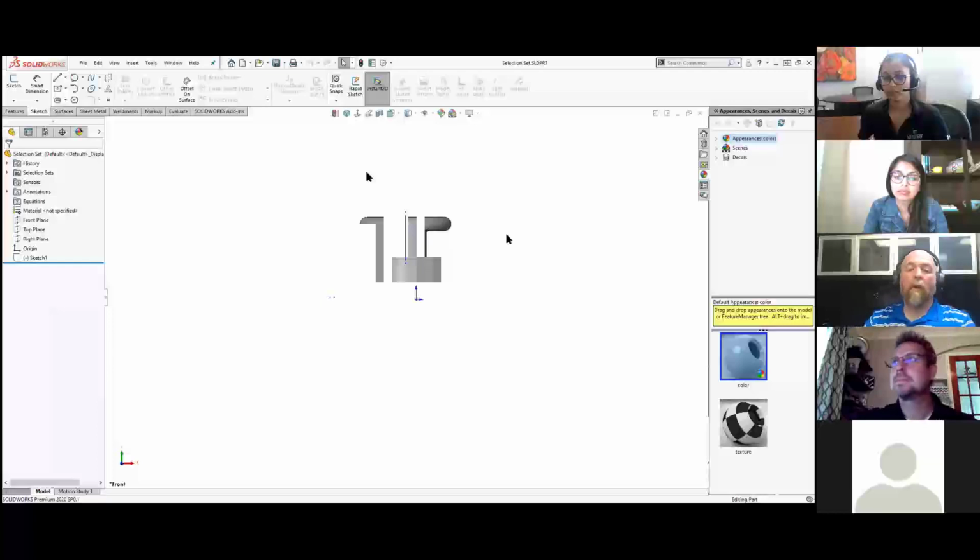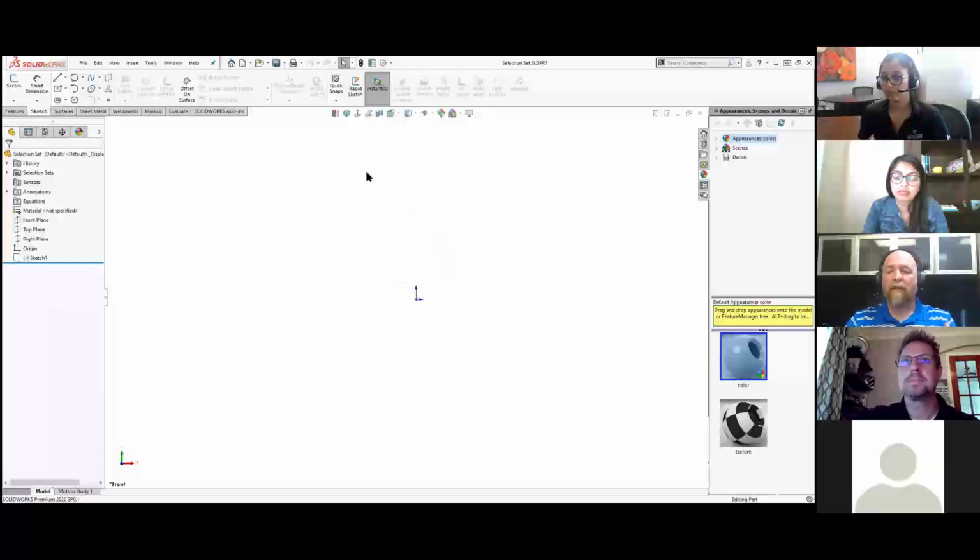I love these when I'm using one face in an assembly for multiple mates, that face as a selection set. So every time I want it, I don't have to zoom in, zoom out, whatever the case might be to find these things. I just click them from the selection set. So I'll go through how you add that and what you can do with it.